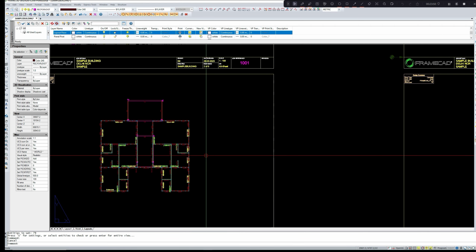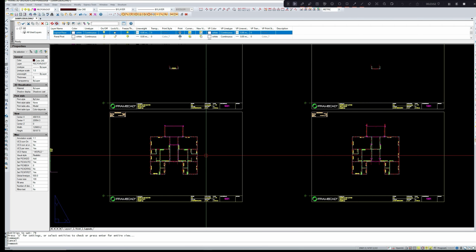First the K braces and then the strap braces. The K braces shall be diagonal between the horizontal members of the panel, and the strap braces shall be from the top of the member to the bottom of the member, a diagonal strap that will act as a truss tension member.